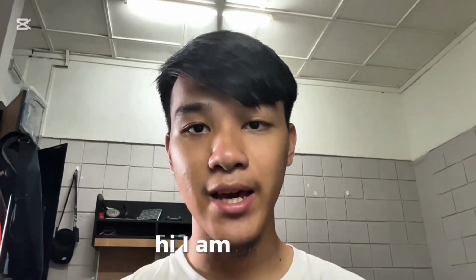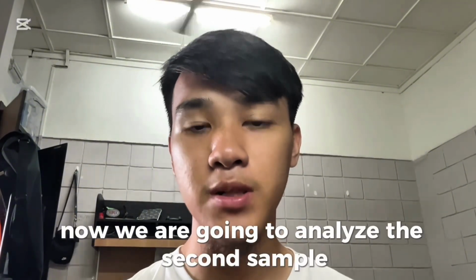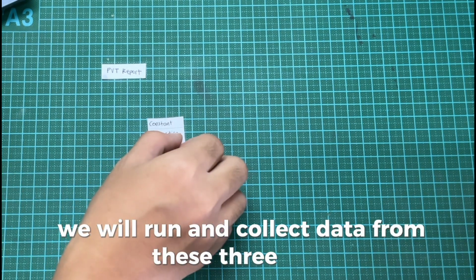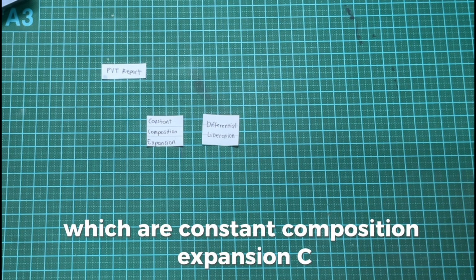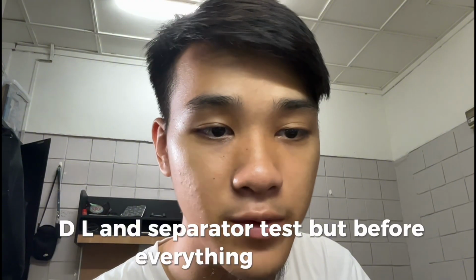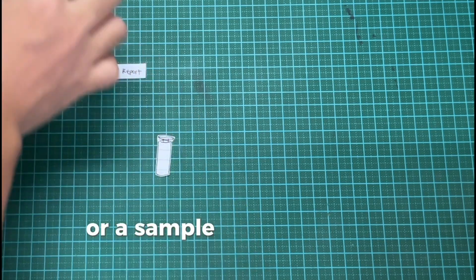Hi, I am Abigail. Now, we are going to analyze the second sample, which is RCL 1016973. If we recall back in the PVT report, we will run and collect data from these three tests, which are constant composition expansion (CCE), differential liberation (DL), and separator test. But before everything happens, we need to make sure the fluids or sample pass the quality check.